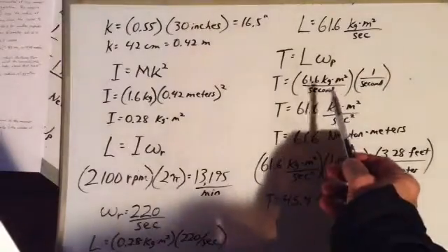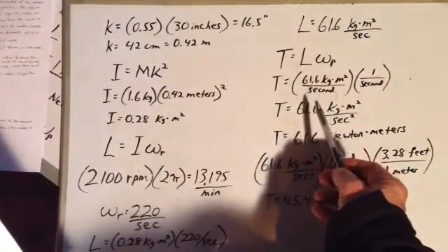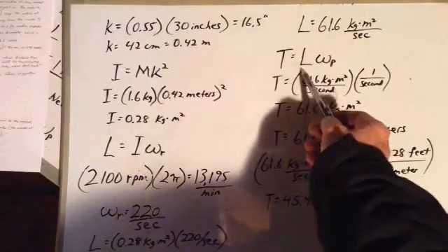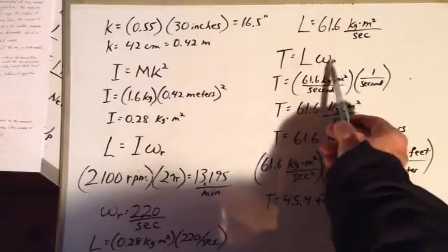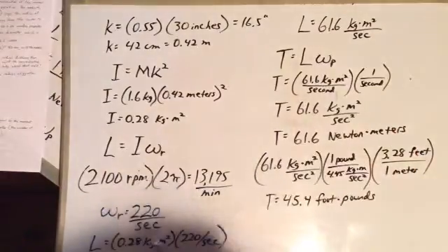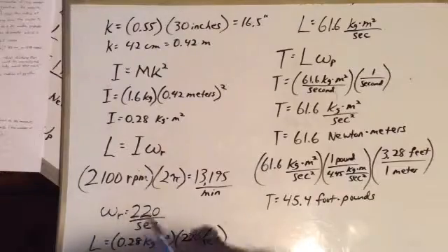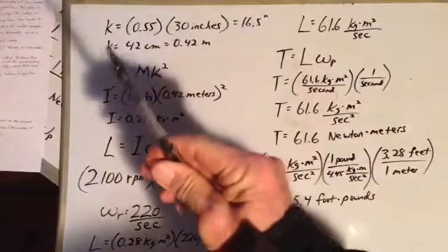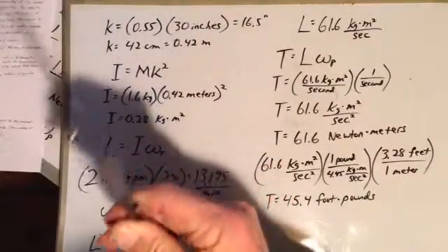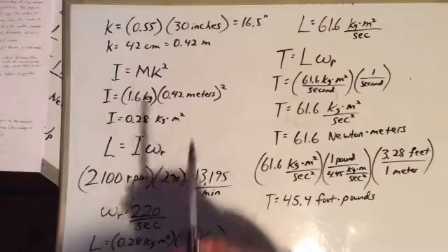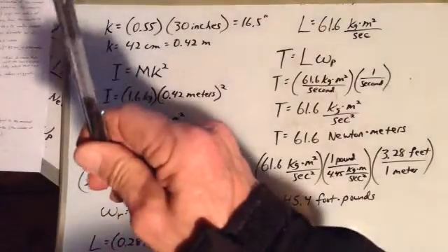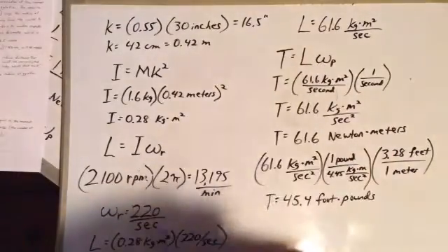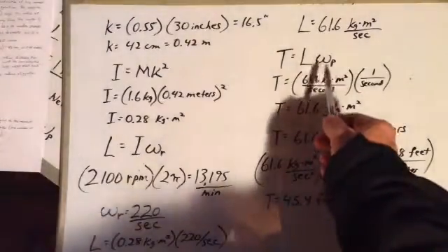Our resulting gyroscopic torque equals angular momentum times the precession rate. Notice this is omega sub p, not omega sub r. Omega r, that's the fast one. That's how fast the propeller is spinning around. Omega sub p is how fast you're changing the axis about which the propeller is rotating, in other words, the propeller shaft. You're aimed up in the sky and then you're aimed down toward the ground. So fortunately that's not near as fast as this is. You'd be in big trouble if it were.